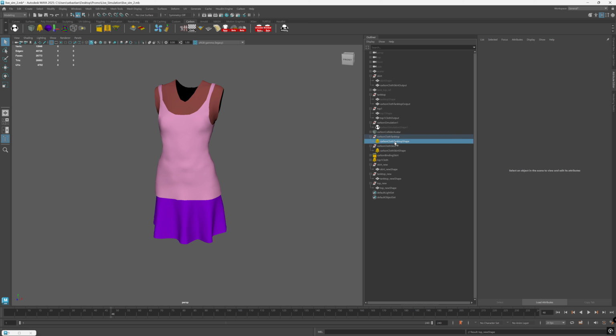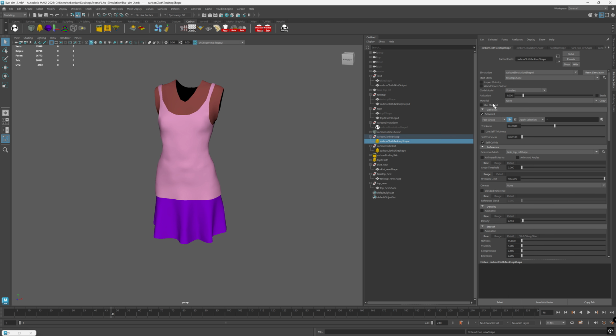Let's go to our cloth node. First one is the tank top. On the tank top cloth node, you can see I have a start mesh and I also have a reference mesh. Reference mesh is because the original tank top I had on the avatar without this shirt. So I actually had a reference to provide to my simulation, which was important because obviously our straps were slightly deformed and I did not want to bake these into the mesh. So make sure when you edit an input start mesh to also have a reference that is unedited so you don't bake in any deformations into the cloth references. All right, what we need to do here, I can keep my reference obviously because I already have one, but now let's point the tank top to tank top new shape.